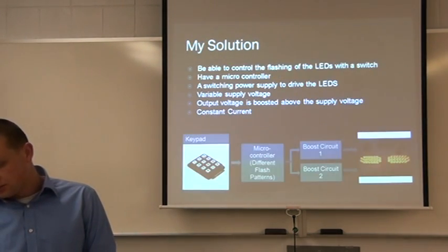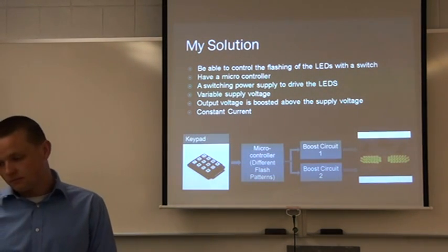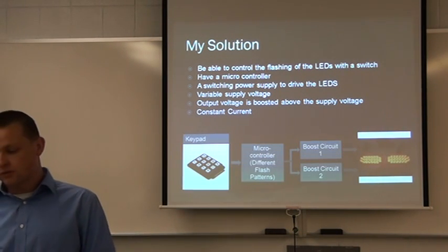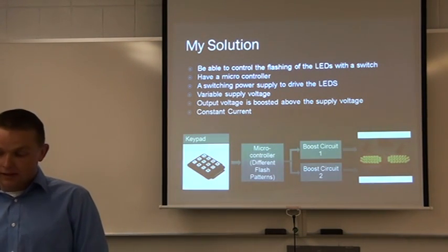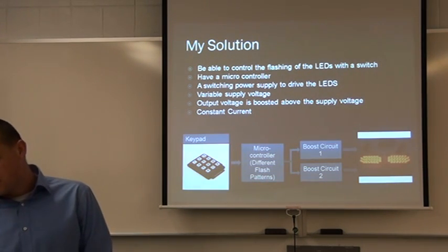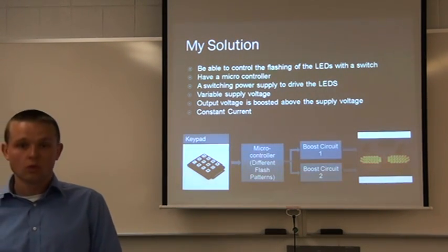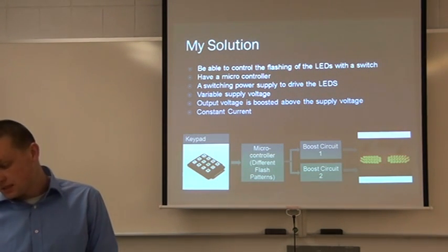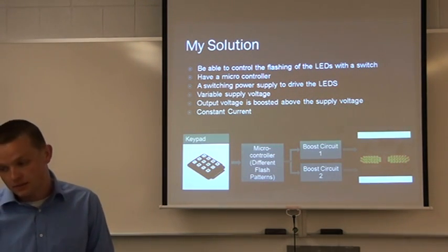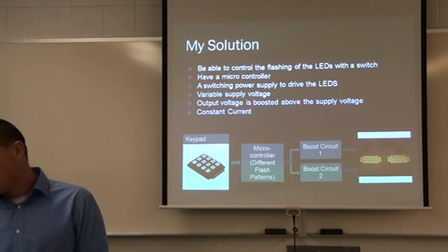So I had another solution. My solution was to control the flashing of the LEDs with a keypad and a microcontroller, and to have a boost circuit where the output voltage would be boosted above the input voltage to control more LEDs with a constant current, because current is better when trying to control the LEDs.